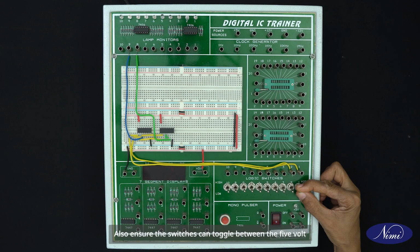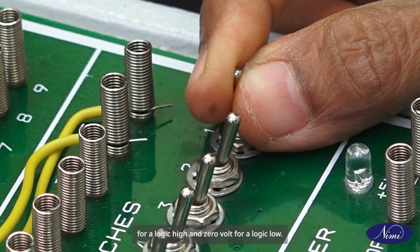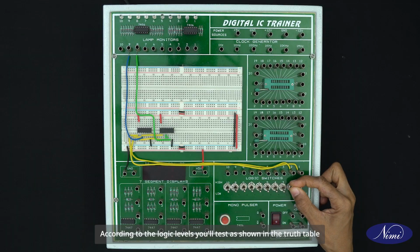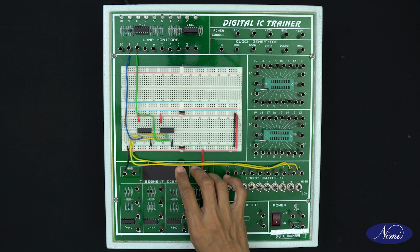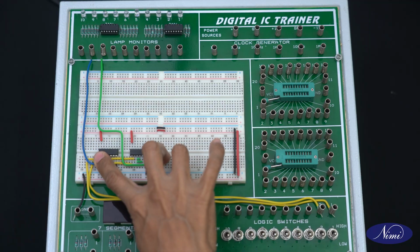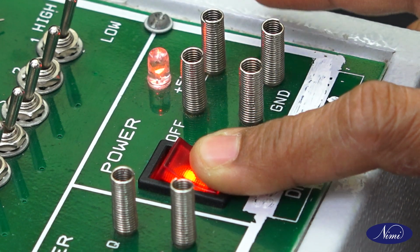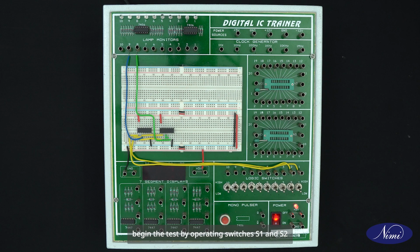Also ensure the switches can toggle between 5V for a logic high and 0V for a logic low. According to the logic levels, you will test as shown in the truth table. Before you power up, get your assembled circuit checked. With everything checked, switch on the 5V DC supply. Begin the test by operating switches S1 and S2. Observe the status of the LEDs for each combination.